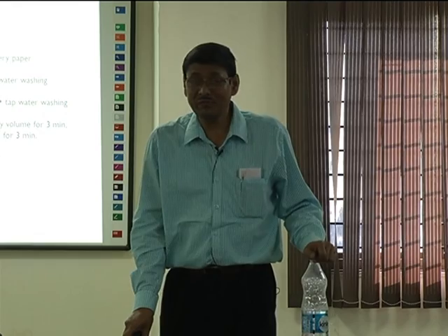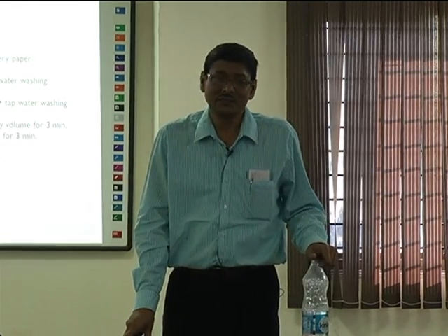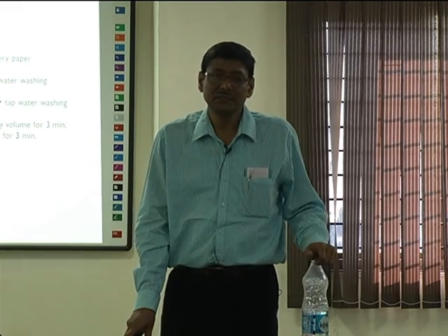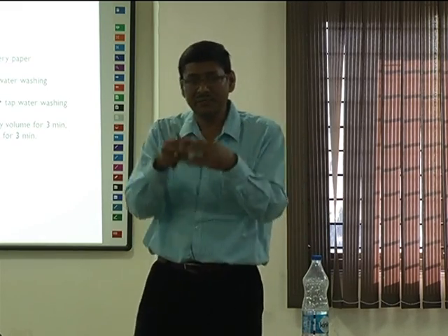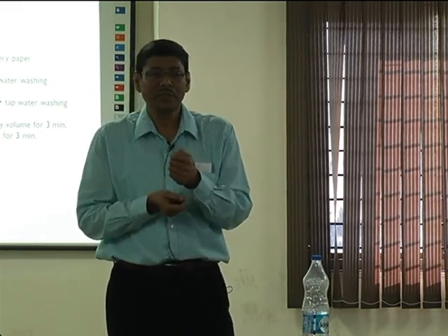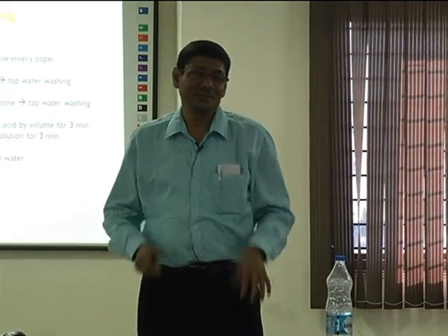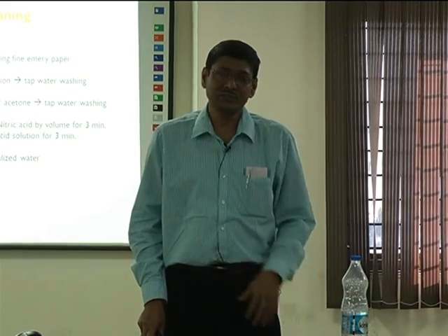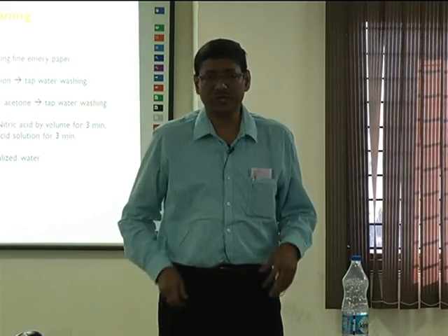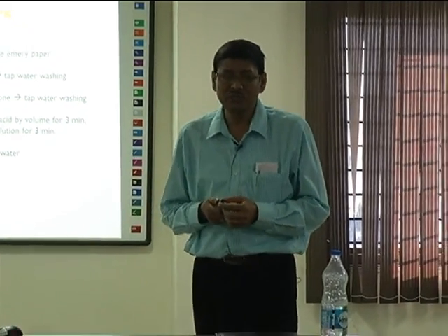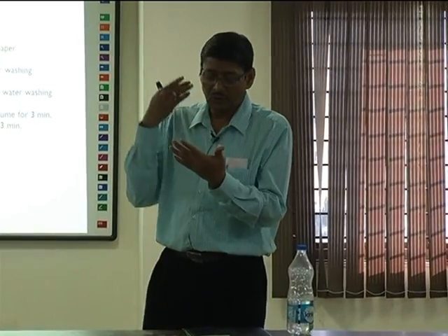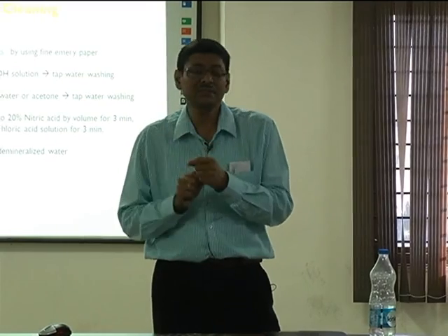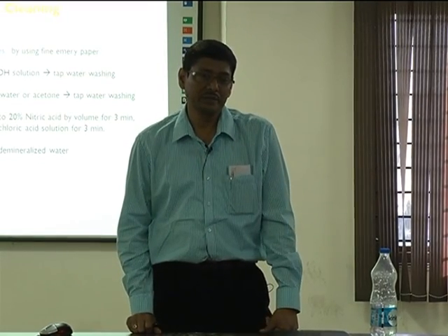If you are not taking proper care while cleaning, then you will not get a leak proof heat exchanger. You will get a heat exchanger that is bonded, but the moment you go for leak testing, you will see that leaks are appearing. It is only cleanliness which will ensure the leak proof joint. For that, you have to ensure that all plates, all spacers, and every space of the spacers do not have any dirt particle.